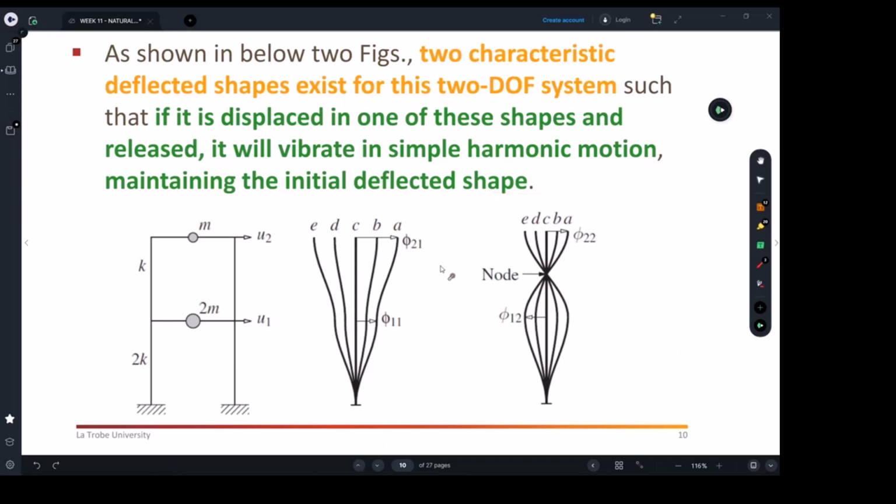So the mode shape usually is the most likely shape of vibration to happen, the weakest, and usually the weakest one is mode shape number 1. In other words, you can say it's the easiest shape for the building to vibrate at. Which one is it? It's actually this one.